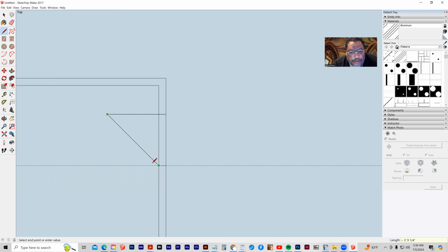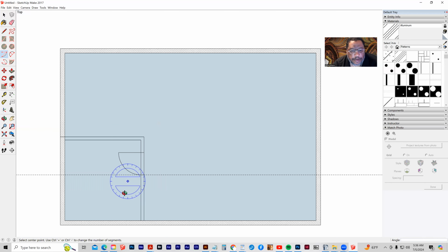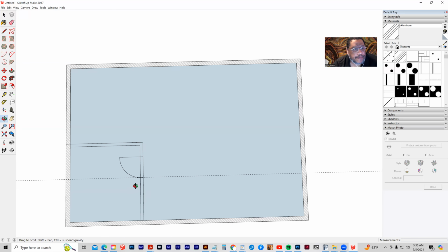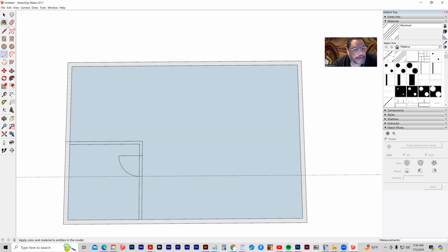And then I want to show the door swing. So I'm going to grab our arc that draws from 2 points. I'm going to click at that corner there, come down to here, and then drag to there. And that's my door. That's how my door would swing. All right. And we can erase these extra lines and take the fill out of the center of the model.